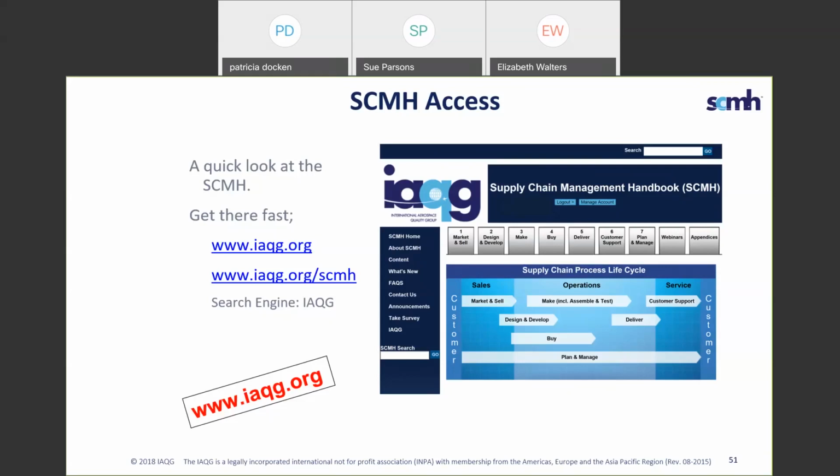Another question: after risks have been mitigated on the PFMEA, what drives me to act on the control plan? Well, anytime that you update the PFMEA, you're going to want to look at the control plan. If you're updating a characteristic, you might be updating an inspection.